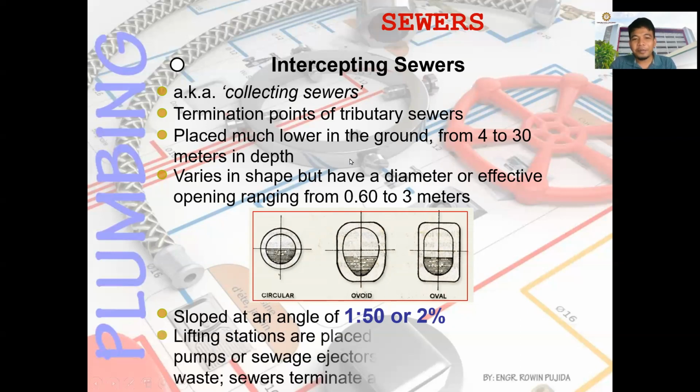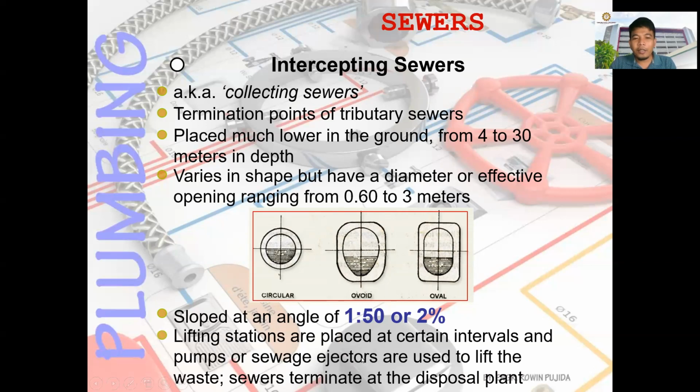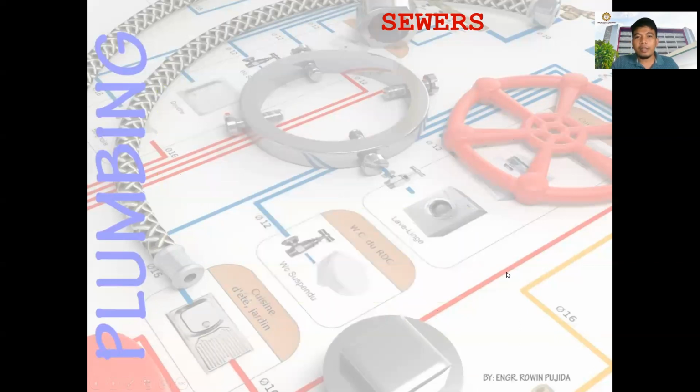Do not just follow the slope of the road. Okay. And then lifting stations are placed at certain intervals, and pumps or sewage ejectors are used to lift the waste. Sewer terminates at the disposal plants.